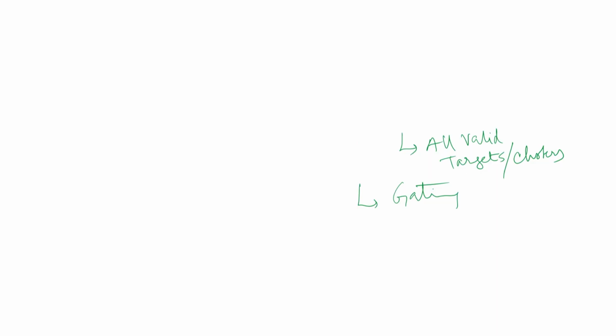For all the gated measurements, there could now be ambiguity. Some measurements could fall in multiple track gates, or two track gates share a common measurement. Some measurements do not fall in any track gate, so that means they could be a new target. Some previously generated tracks didn't find any measurement, so that means it is either a misdetection or the target is dead if it is prolonged. So, these are the 3 possible combinations out of your gating: 1, 2, 3.